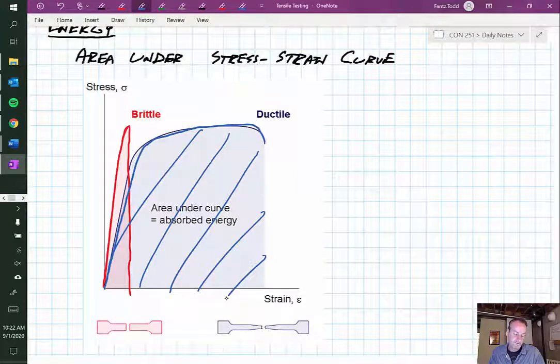And so if you were, say, designing for an earthquake, I think I mentioned this last time, the steel buildings would still be standing after an earthquake, where concrete buildings tend to fail. That's because the steel can absorb all this energy. It's that whole bending but not breaking thing, moving back and forth and waving with the earthquake, versus concrete, which is very brittle, so it doesn't have that ability to absorb the energy, and it fails right away.